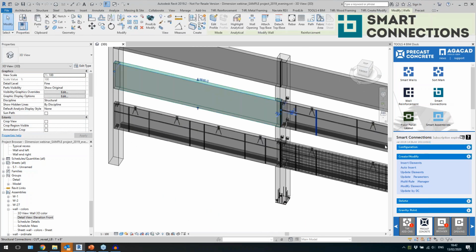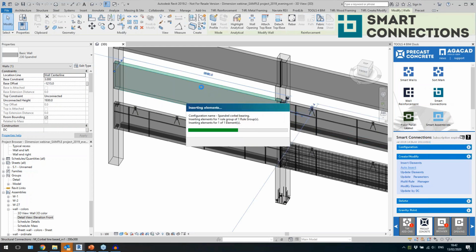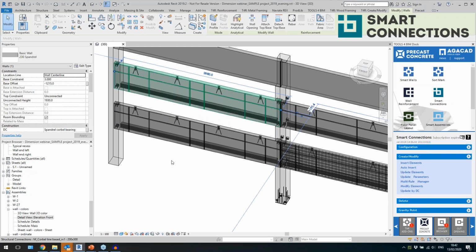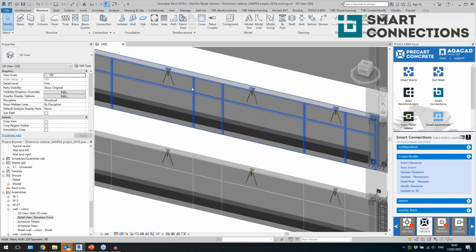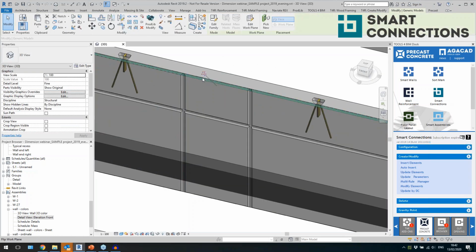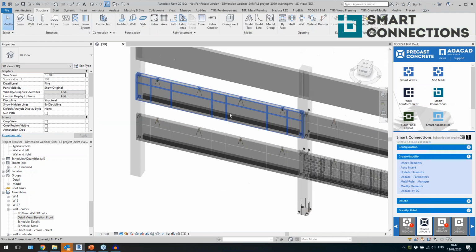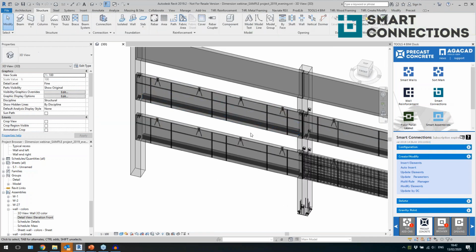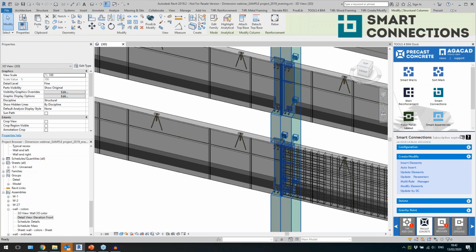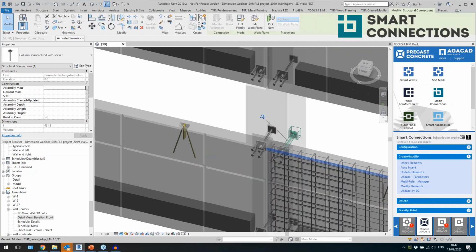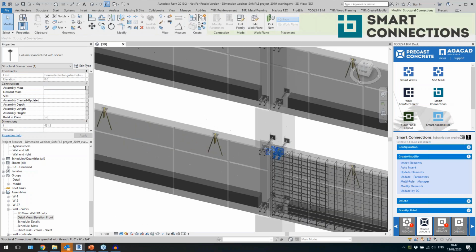So at least one of the options here. Of course you can use it in many other elements, like spandrel wall, for example. Here I have lifting points, I have reveals, I have fillets to cut my wall, I have supporting corbel over here. I have column with these bolts, which is placed at the location of these plates.